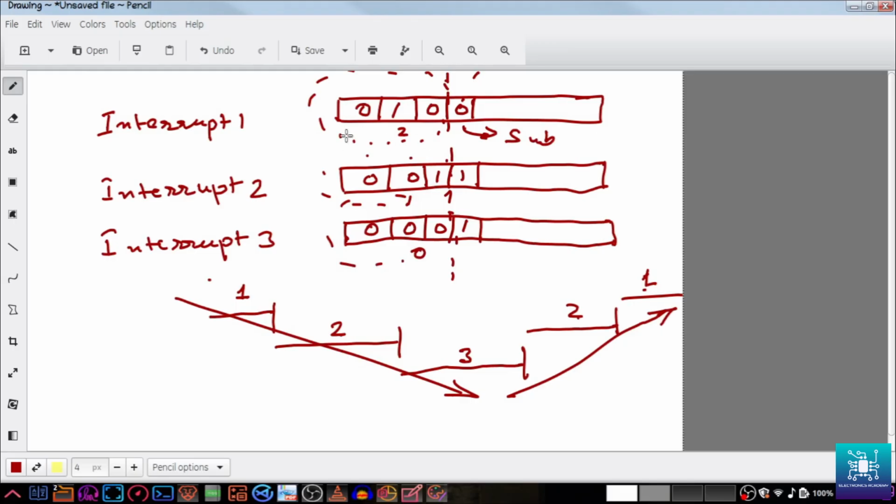Funny things can happen if your priority bits are different when you change the group priority and sub priority, but then this is how it is. The behavior is going to be the same, because though the grouping changes, interrupt 3 still has the highest priority. So this is how group priority and sub priority is decided in ARM Cortex M4. We will see an instance of preemption between SysTick and external interrupts, and this will be demonstrated in code.